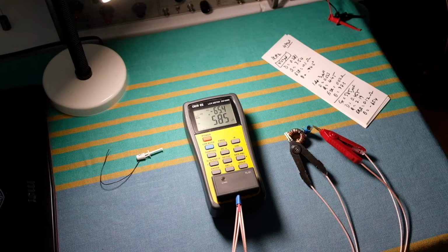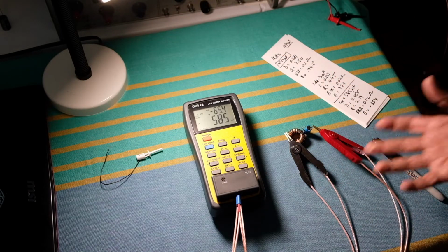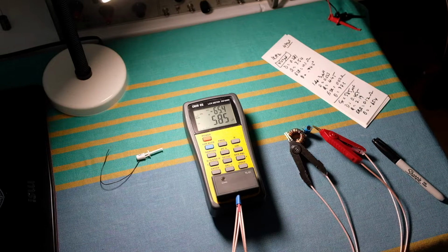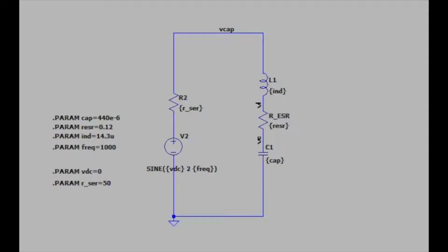So effectively these meters are actually measuring the energy in this system and calculating the effective capacitance for this combination of RLC network. This slide shows the simulation schematic for the previous experiment I just ran using the capacitor and the series inductor.